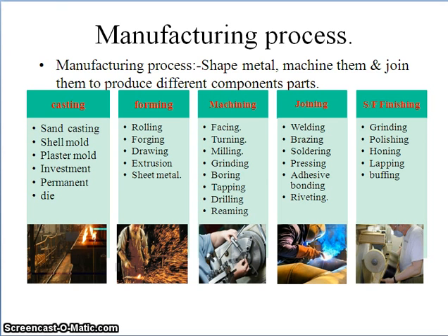It is the process in which the metal is loaded in a container. The container is closed from one side by a die which has the necessary opening, whereas at its other side it has a plunger or a ram. A dummy block is placed between the plunger and the metal in order to protect the plunger from the adverse effect of the heat. When the plunger or ram applies pressure, the metal gets compressed between the walls of the cylinder and the walls of the die, and it is forced to move through a single opening so that it can take a similar shape.